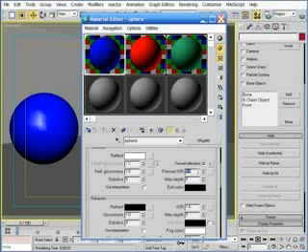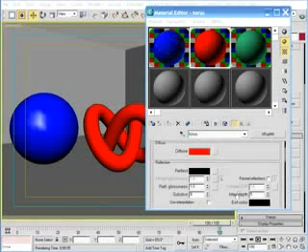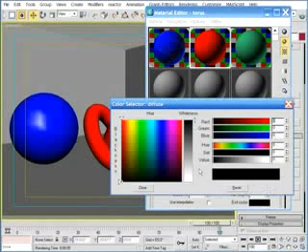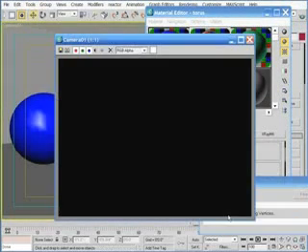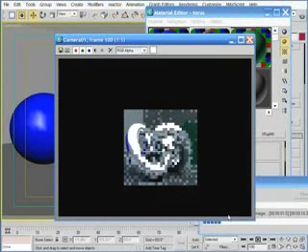Next, I want to talk about another quality that VRay materials possess, and that's the max depth value. The max depth value specifies the maximum number of times that VRay will allow light to reflect from one surface to another. Depending on the exact field of application you're using 3D for, you will probably need to change this value only rarely. To see its effects, I'll maximize reflections on the torus in the scene and render as is.